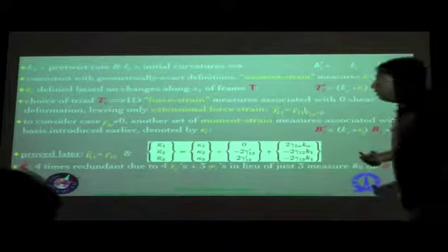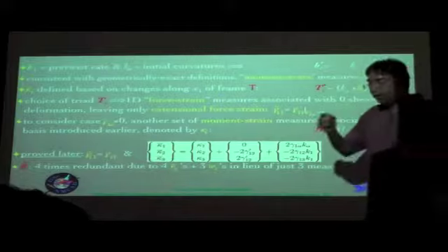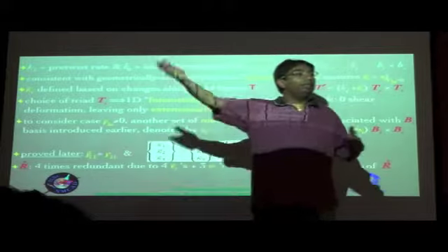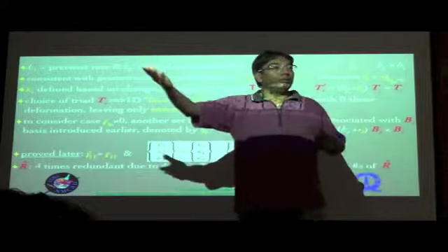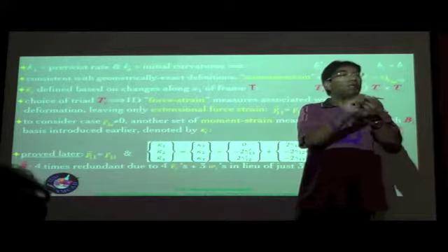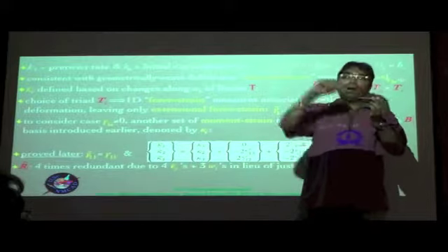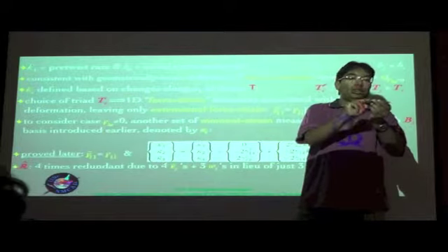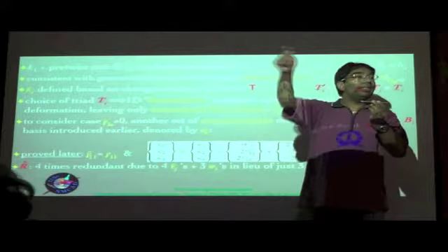Next, your r hat is an important thing to see, that basically how do you determine r hat? R hat is a vector, so like any other vector, it basically has three quantities along three different directions as the measure numbers, and once you know those three quantities you would be able to determine it. So in other words, you had an undeformed beam, you are monitoring just one particular material point in this beam, somewhere along the length, somewhere in that particular cross section, and now after the deformation it has gone somewhere else. The number of quantities you need to determine that motion is just 3, okay, because in 3 different directions how much it has moved by.